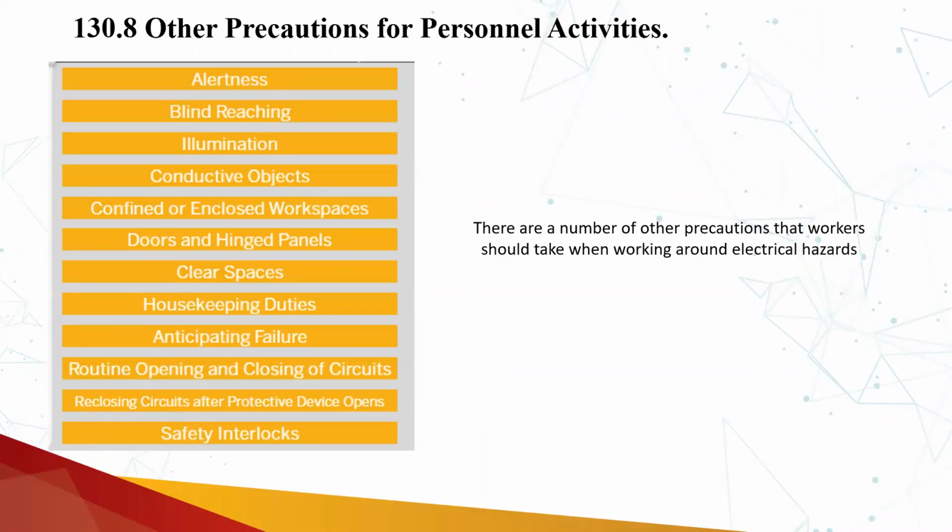If this is with the equipment which are considered to be in normal operating condition, or the equipment are in normal operating state, then this routine operating and closing of the circuits are normal operations. But if you doubt about the assets, whether the assets have been maintained, or whether there is some evidence of impending failure with those assets, then this routine opening and closing of the circuits will be considered as an energized work rather than a normal operation.